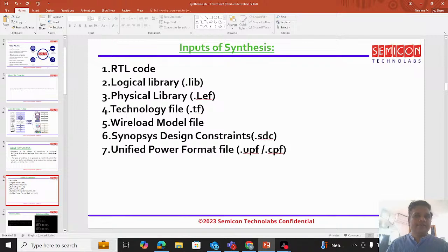They store the data. So generally that's why, from the timing perspective, we have reg to reg, where we have combinational logic in between two registers, and the operation or the data transfer between the registers is controlled by the clock signal. Okay, now this physical library is again given by the foundry, and this is applicable only when we are doing physical aware synthesis.